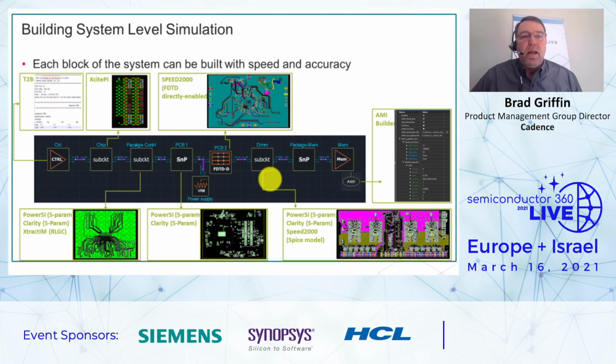And I wouldn't take away that methodology early on in the design cycle, but there's going to come a point at these kind of speeds where you're going to need a little bit more reliability, a little bit more confidence, if you will. You're going to need to extract that using a full wave 3D field solver.